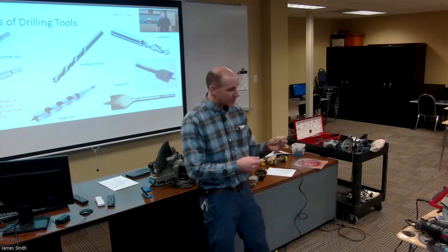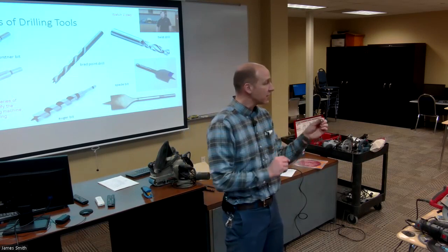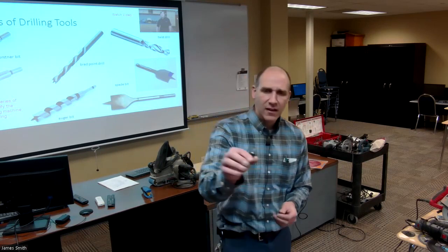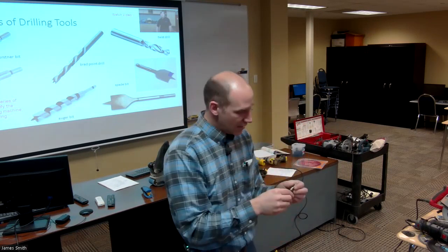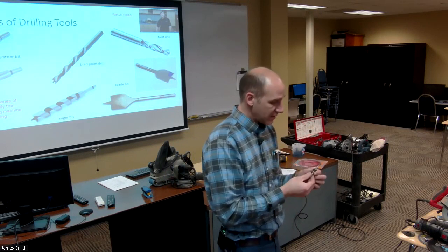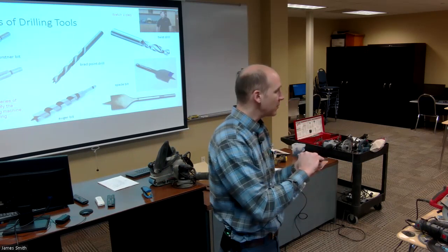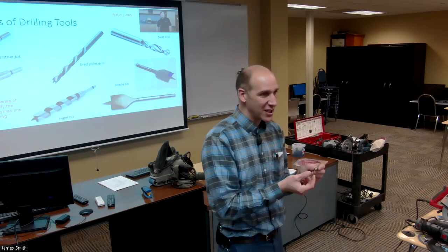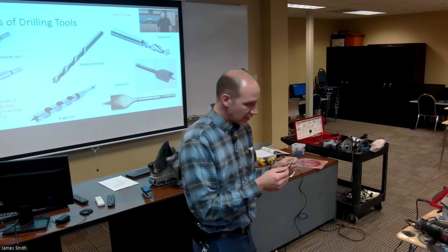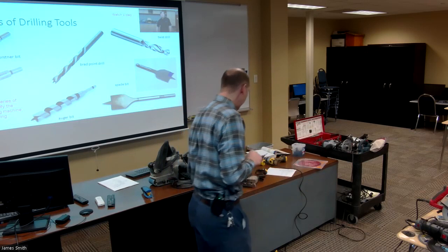Unless you've got one of these fancy combination pilot drill and countersink bits. These are fantastic. I don't know if you can see that, but I bought this one from Rockler for a little bit of money, and I've been very impressed with it. A lot of these, it's easy to run them too fast, especially with a taper bit, and then they get hot and start changing colors. You don't want to run these very fast. Run them at a slow speed so you don't lose your temper. But these are a really good bit, and it combines operations.